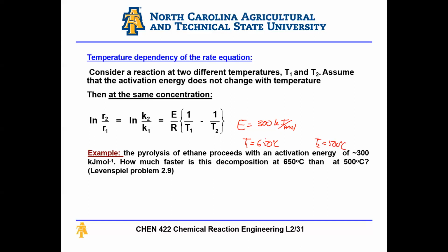One very important thing to remember here is you need to always convert this to Kelvin, right? The temperatures here always have to be in absolute units. Celsius does not work, Fahrenheit does not work, and absolute units refers to either Kelvin or Rankine. If you solve this in Celsius, you're going to get a very, very wrong answer. Solve this in Fahrenheit, you're going to get the wrong answer. You need to convert it to Kelvin or Rankine.